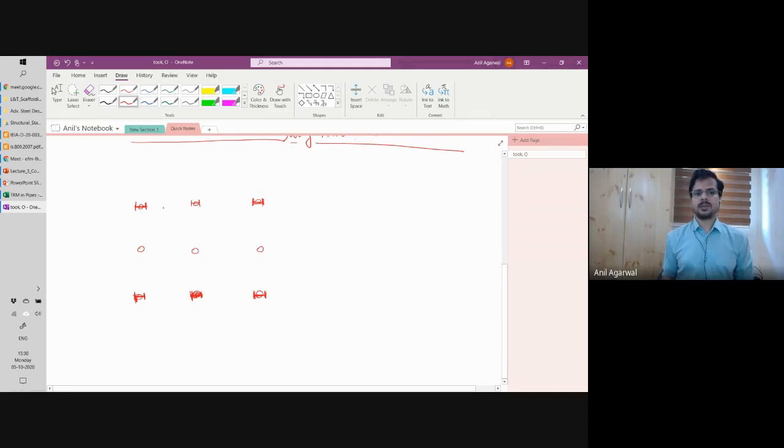Now what happens is that this is fine. So now I can connect beams between these columns and make them rigid frames. So I can rigidly connect these beams to the columns, right? Because I have got flanges of the columns connecting to the beams. This is the column flange, and the beam is coming and meeting it here. And I can very easily weld, or there are hundreds of ways in which I can provide this rigid connection between the beam and the column. I'm just showing you one. So I can weld the flanges of the beam to the flanges of the column. Perfect. That is a rigid connection.